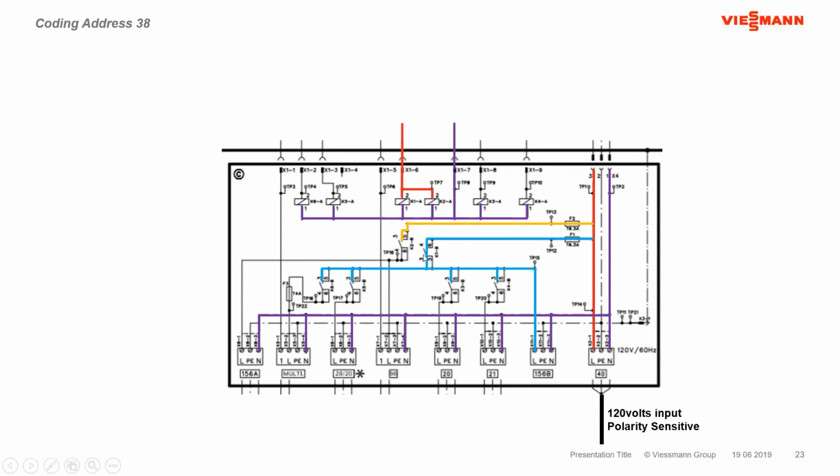So we've closed the contact here, and now the power sits at all these relay outputs, waiting for those relays to close, and we have power at 156B. So right away, there's power at the 156B. Remember, 156B you can use for some sort of an outlet if you want for power, but it is protected by F1. So 6.3 amp fuse here.